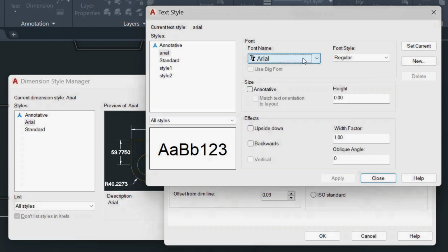Click on the area. Then here area already is okay. Text type no need to change. This all no need to change. Last time I already show you how to create the text style. This one is totally same procedure. I won't show you very detailed because I want to save the time. You just choose the text here only. The rest then no need to change. It's okay. Then click on set current and then click on close.